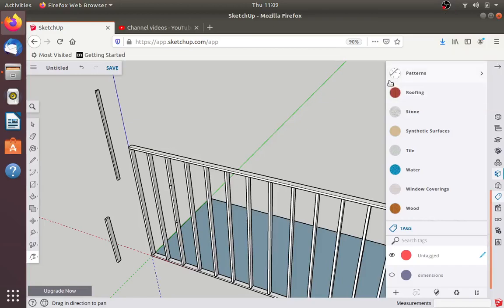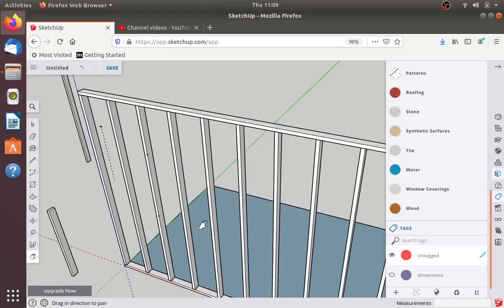This video is part 2 for the tiny house wall framing. I'm just going to show you how to put a window into the wall the easiest way possible, also adhering to the generally accepted building standards. First thing I'm going to suggest, when you're deciding on more wall or more window size rather than location, is using the existing studs to help you determine the size of the window.